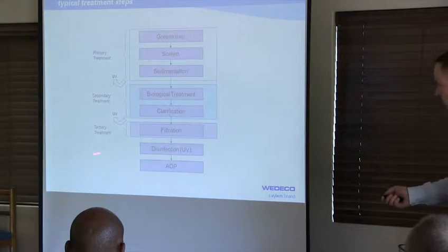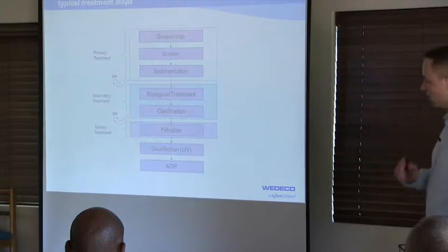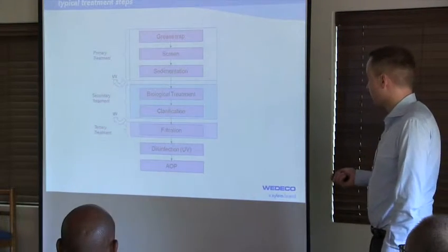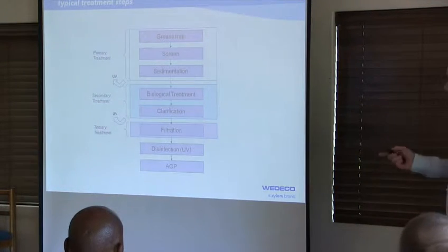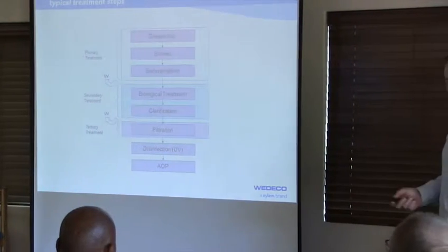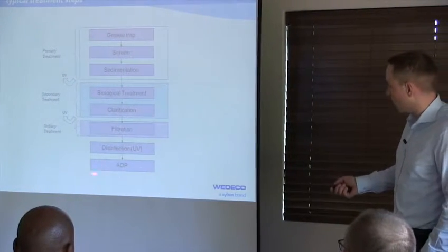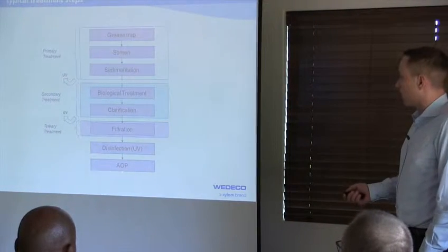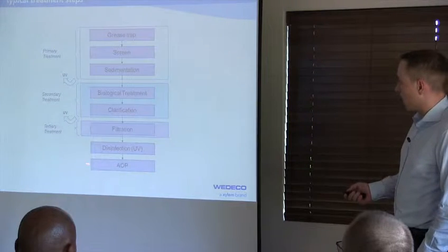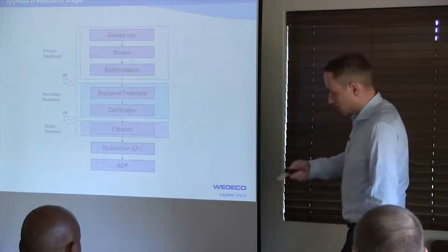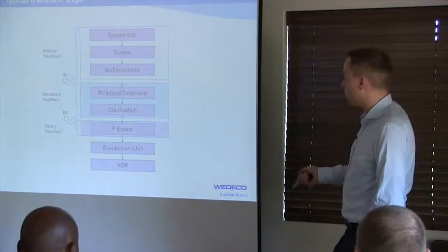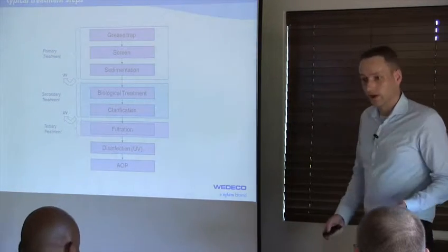And based on what you want to do with the water afterwards, you might also have advanced oxidation processes, so that might be combined processes with UV and ozone, or UV and peroxide, or ozone, peroxide, or all three together.